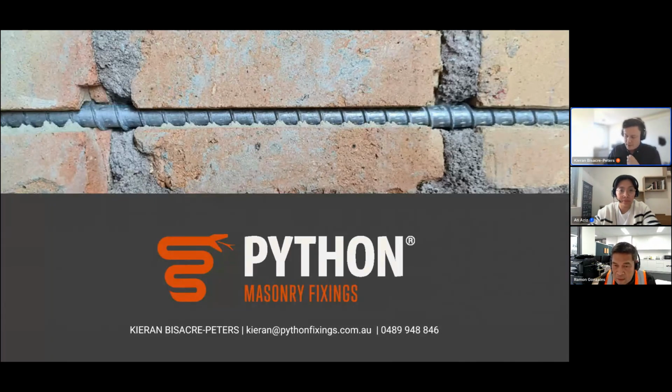Yeah, again, as I mentioned, we've had a lot of success with the use of screw anchors for remediating brick ties that are corroded, just due to the better engagement that you get between the mechanical thread of the screw and the substrate.